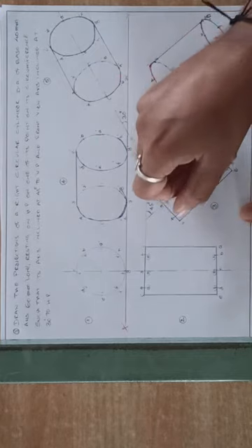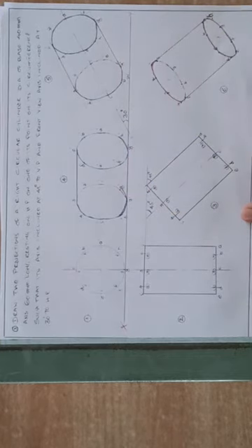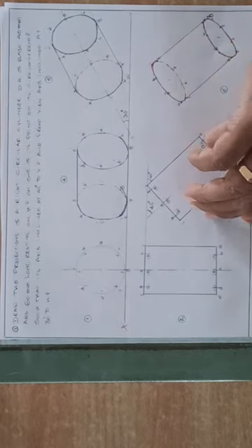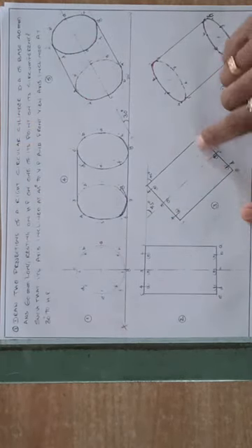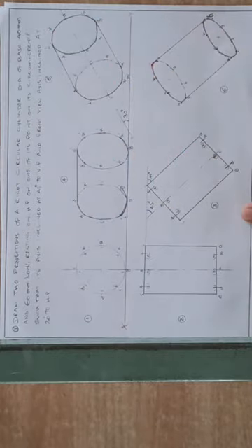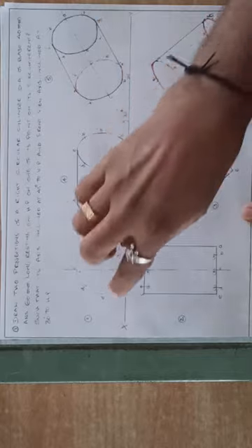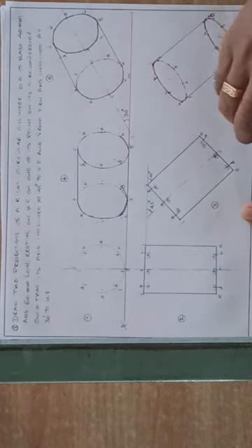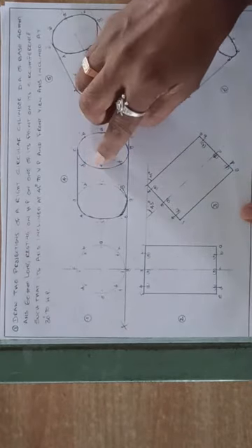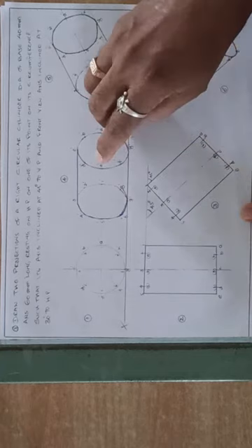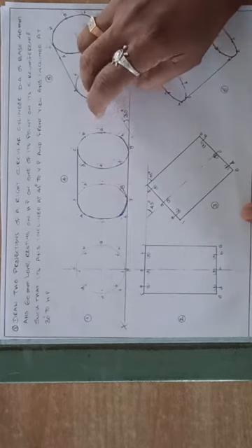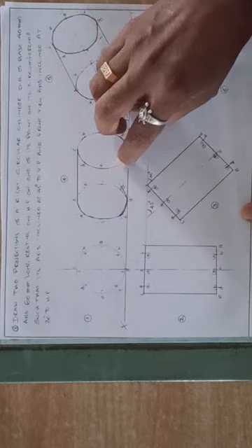If you want, you can join it also, but with very thin lines, right? Now draw the projections upwards. Take the first face. Don't project all the lines at a time. First take the face, project upwards, project horizontal lines. Now E vertical, E horizontal, okay, F vertical, F horizontal. In this order you will get points A dash, B dash, C dash, D dash.